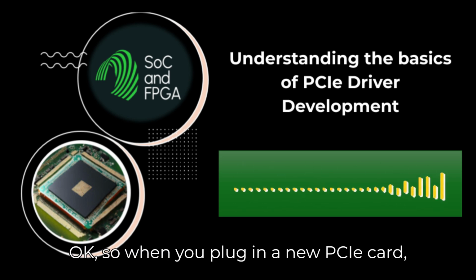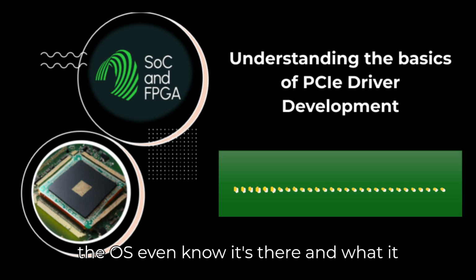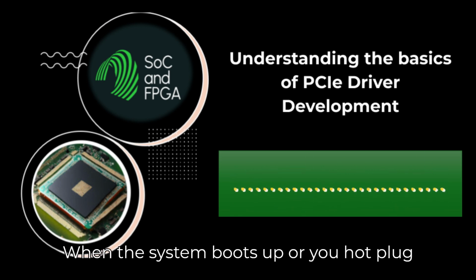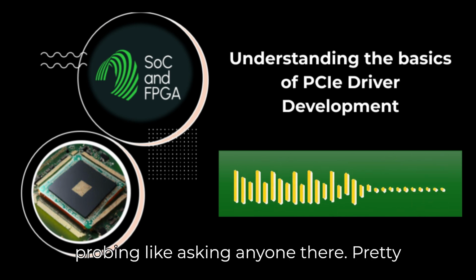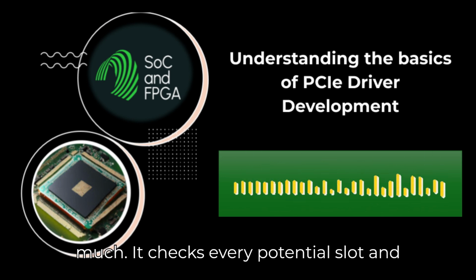Okay, so when you plug in a new PCIe card, the system magically finds it. How does the OS even know it's there and what it is? That's the plug-and-play magic, managed by a process called enumeration. When the system boots up or you hot plug a device, the OS or the system firmware, like UEFI, starts probing the PCIe bus. Probing, like asking anyone there? Pretty much. It checks every potential slot and location.